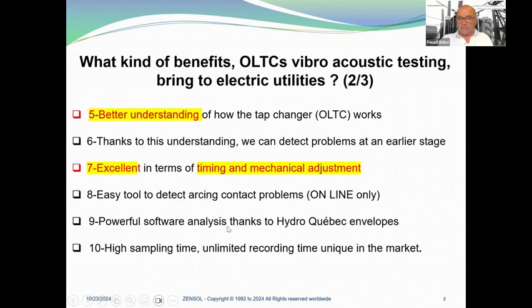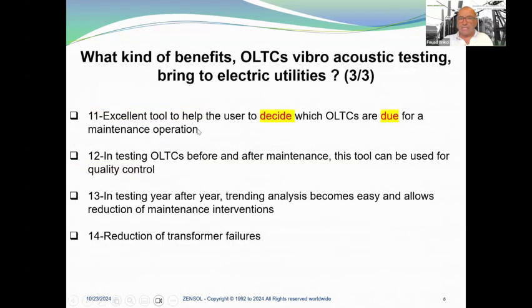And we have Hydro-Quebec envelopes, and in the software, it's easy after to analyze the vibroacoustic. We need a high sampling rate and an unlimited recording time, which is unique in the market. And it's an excellent tool to help the user to decide which OLTCs are due for a maintenance operation. For example, if you have 20 transformers to maintain in a period of time, you can do the quick vibroacoustic test, very quick with the motor current combined, and then after you can decide which transformer has to be